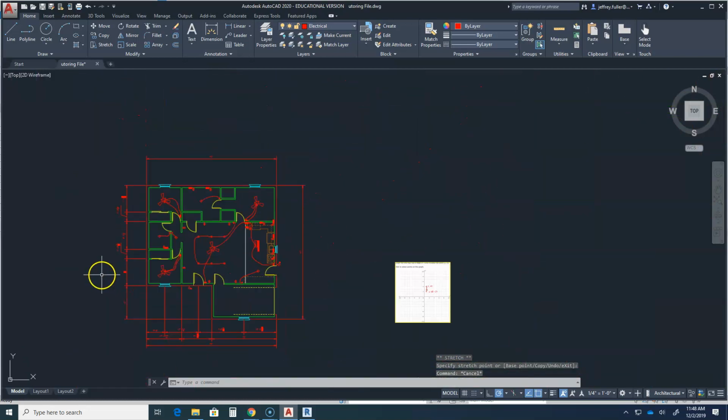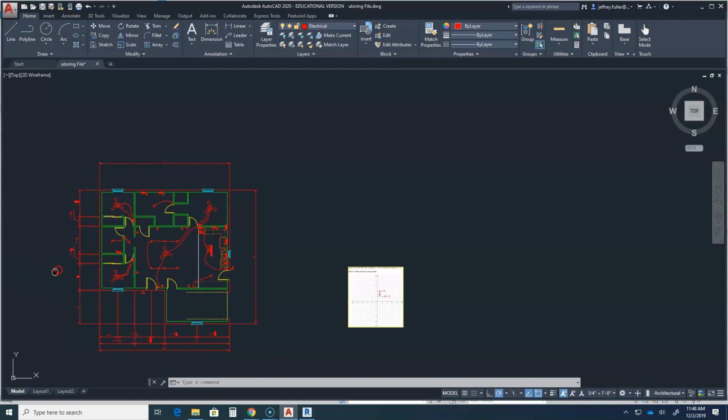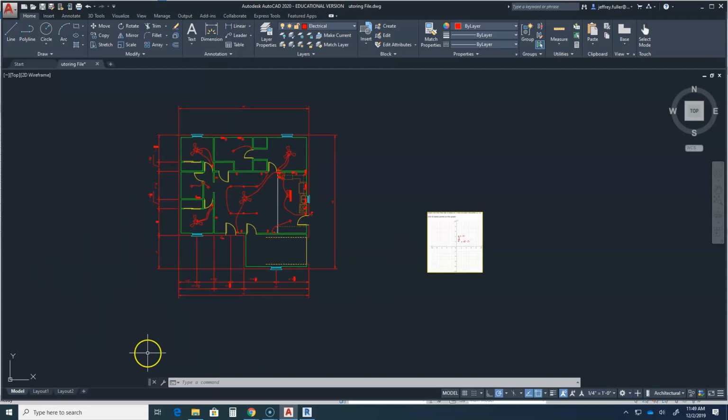Okay, so that would be on that side, the major walls, and any windows would be on the next line if I had them. But anyway, hopefully this explained everything for you, and that you're able to fully dimension your residence. Again, you have all three lines on the front or the south side of the overall, and then the major walls, and then doors and windows. Over here on the right side, same thing: overall, major walls, and then doors and windows.